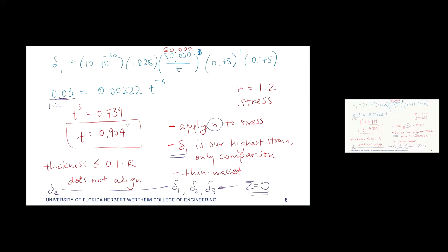What was the effective strain look similar to the principal strain? That's one. So in this case, when I talk about some equivalent strain, the question is whether it's a similar expression to delta 1. It's not. So what you can do is, if you're switching from a stress-based failure criterion to a strain-based failure criterion, you can sort of express an effective strain as like a von Mises strain.